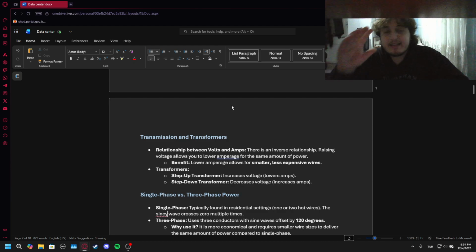Let's say you were using 10 amps and 100 volts; you come out with 5 amps, and that 100 volts becomes 200 volts instead. 200 multiplied by 5 is 1,000, and on the other side, 100 multiplied by 10 is also 1,000, the same amount of power.